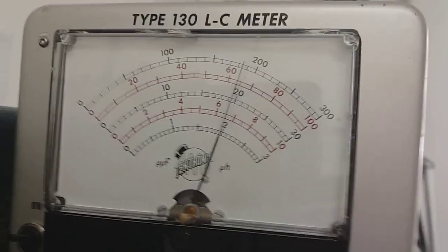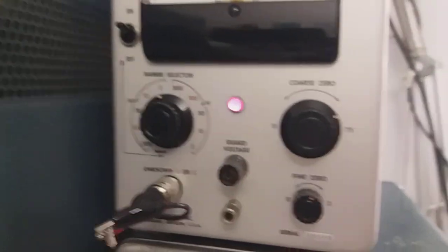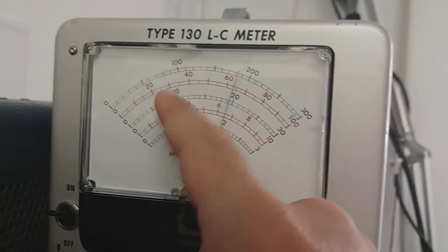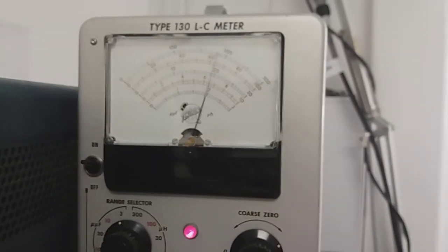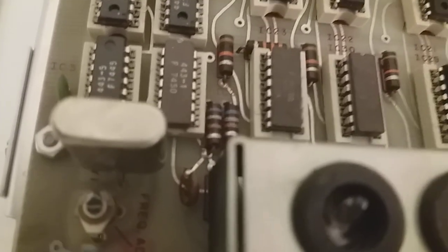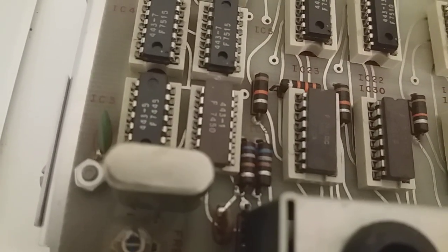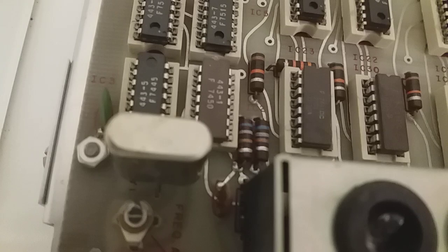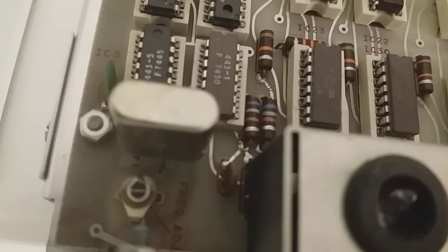So with this nice LC meter, we are able to do such things and much more. That's the nice bit of this meter, not so much the capacitance range, but this one. But anyway, this is for another video. So I'm going to use one of these trimmer capacitors and replace this 2 to 16 picofarads capacitor here, and let's see how it goes. Hopefully the lower capacitance won't stop the oscillator from working, and we can get closer to the frequency we need. So I'm going to replace this and come back.